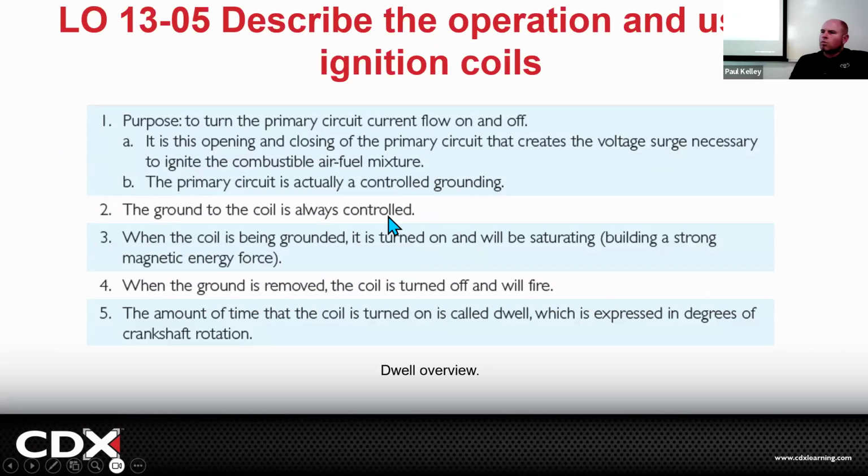What controls it really depends on what type of ignition system it is. We're talking a lot about in general, and then in the end, we're going to start nailing it down: this is how this system does it, this is how this system does it. But you know what they all do? They all give it 12 volts and pulse the ground to start the spark. Give it ground for a while to charge it up, take the ground away, poof, and make the spark.